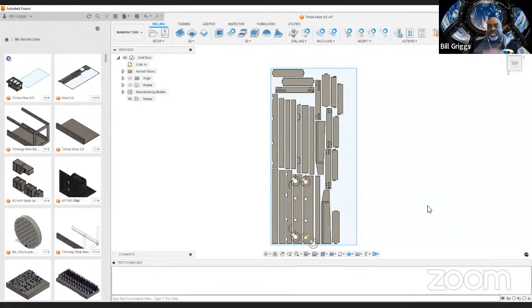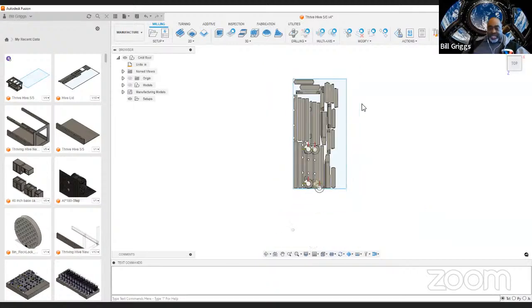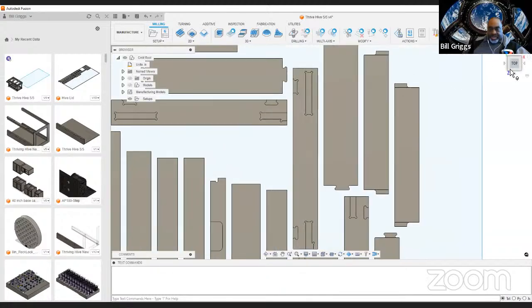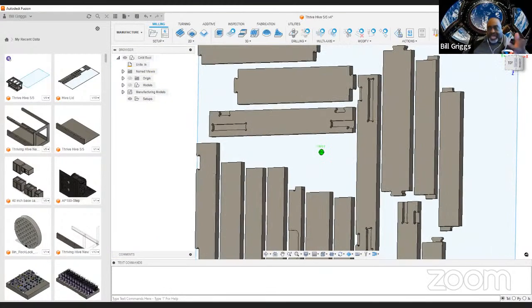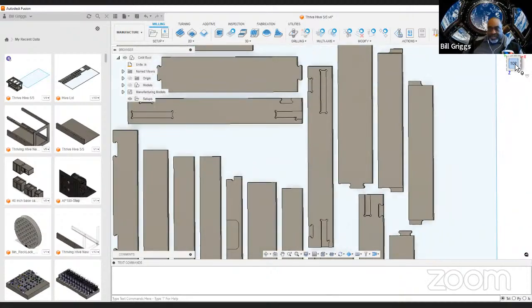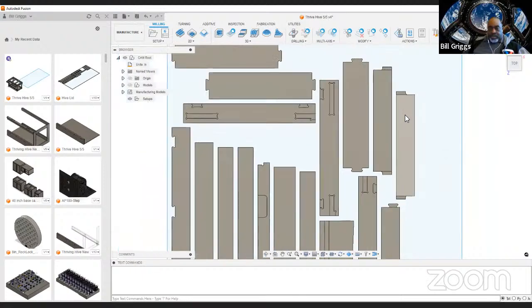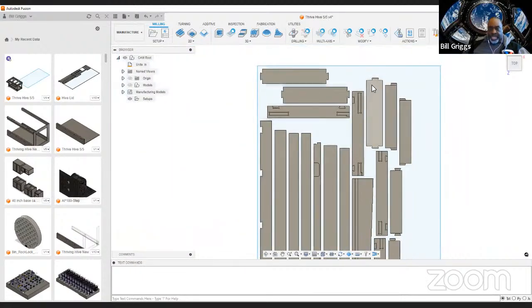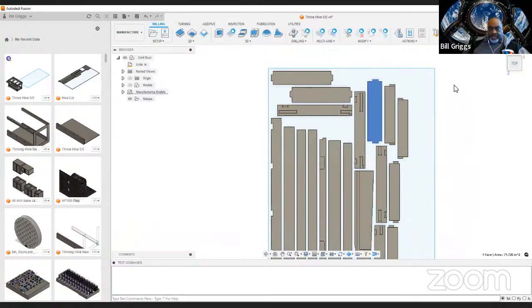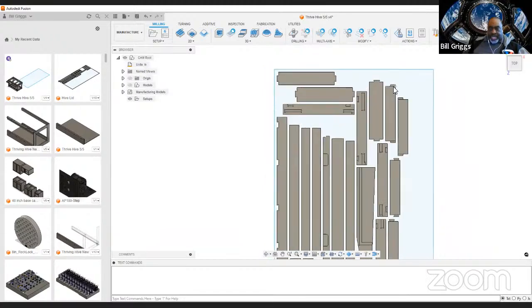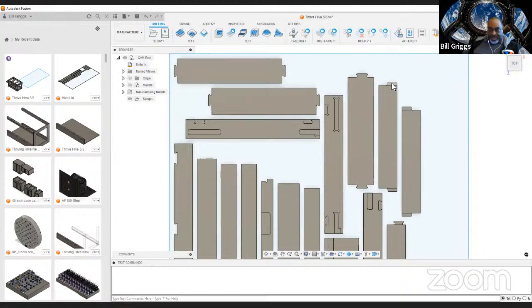Pretty good. So I'm just going to cut to the chase. To make this happen the way you hope it will, you create a sketch, an offset sketch plane. Each of these parts down here are 3D parts. They have length, height, width, dimensions, everything that you would see. But for the vectors you need to create, all you need is outlines for this type of part. For ones that have tabs on them, you need an outline and a pocket outline.